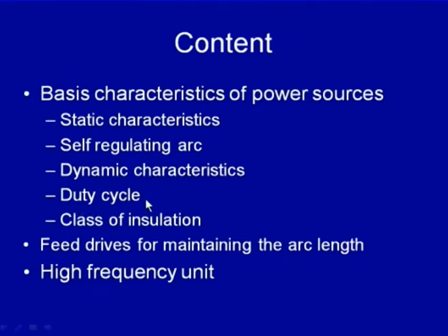The duty cycle is another important factor related to the welding power sources, which indicates how long welding can be done without interruption over a period of 5-minute cycle time or 10-minute cycle time, depending upon the kind of standard which is being followed. And it is affected by the welding current which is being used for the welding purpose.